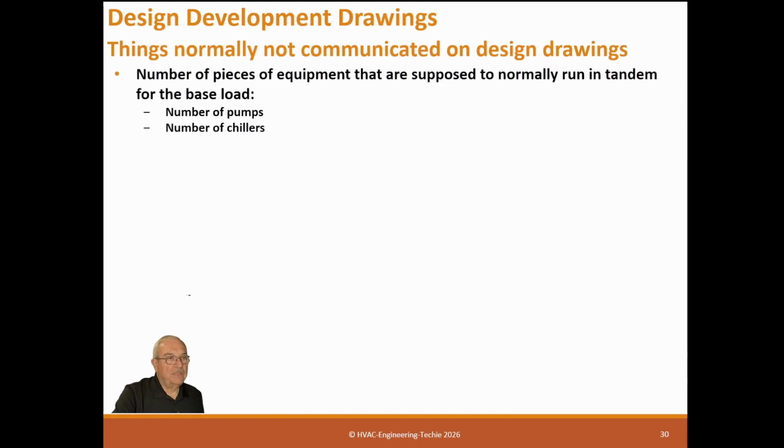So, number of pumps. And remember, pumps are unique, and fans have a unique deal: if you have one pump and you add a second pump, it doesn't double the flow. Depending on the shape of the curve, it goes down after every additional pump. I have seen some central plants that were piped, they looked like they weren't headered, but they were actually headered, and they had like 8 or 9 pumps on a header, which means basically the last couple of pumps were doing nothing. They were just burning electricity, not actually producing any flow.